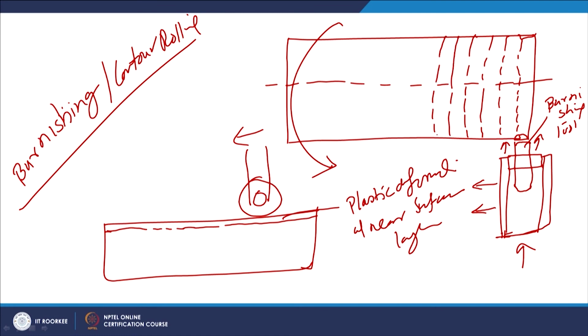Since in burnishing the localized surface layer deformation is achieved by pressing the burnishing tool against the substrate, the required effects of work hardening and grain refinement, and if any transformation takes place, the transformation hardening benefits, can be exploited for enhancement of the surface properties.